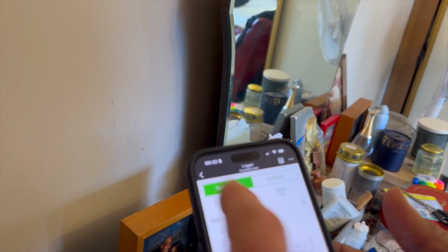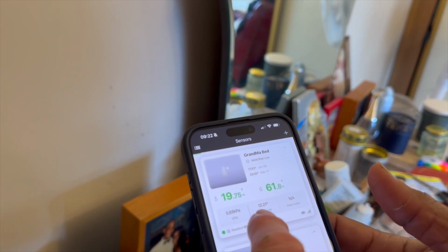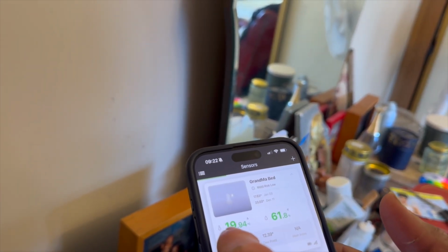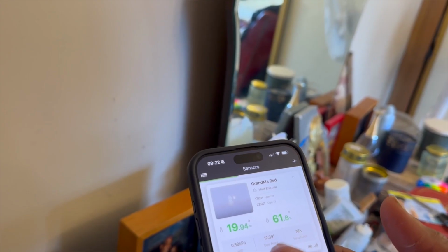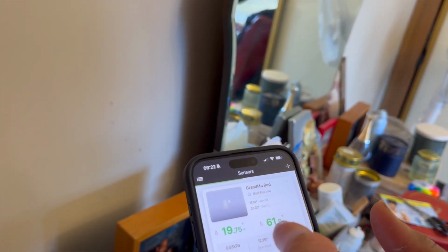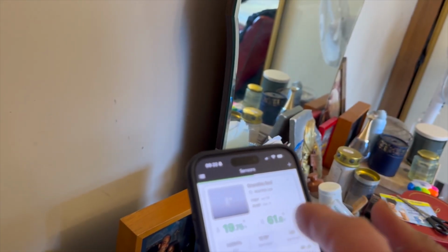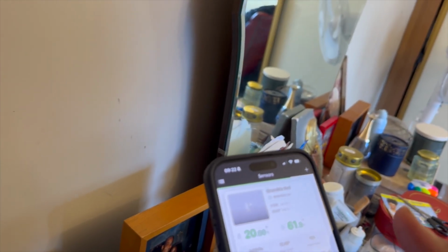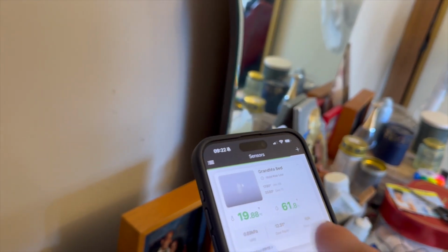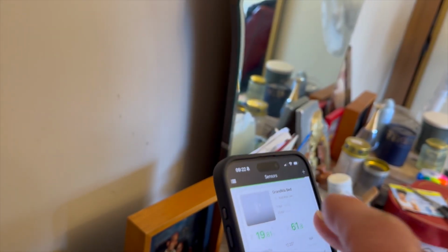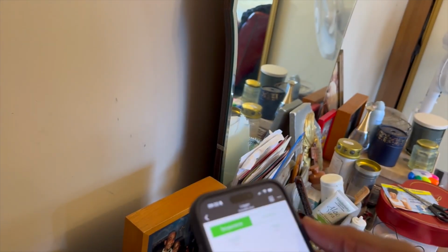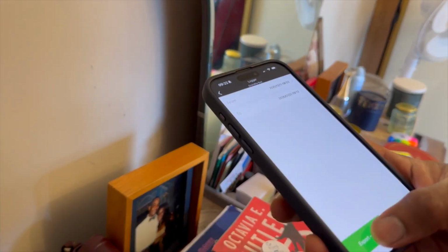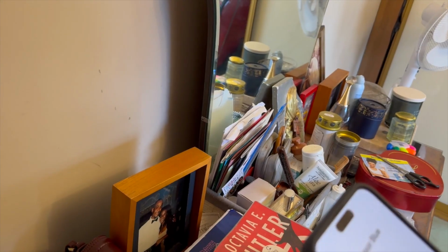So if you take 8 from that, it gives you 12, and that's the dew point. So 100% minus 60, I just round it, divided by 5 is 8, and that gets you to that. So that's how you work out dew point quite quickly. But it shows you the dew point anyway. So if you press the number again, then the calculator sign top right, export sign top right, and export CSV, and then send it to myself, simon@dampsurveys.com.